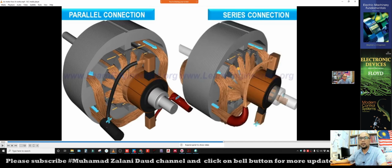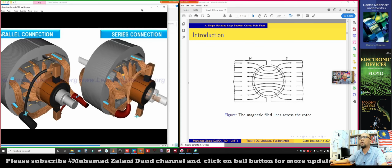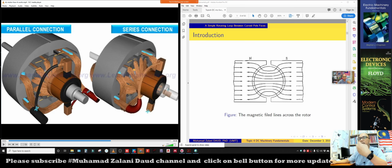Okay, so as you can see in that video, whether it is a motor or a generator, it works the same way, where the commutator is used to convert the AC behavior inside the machine into the DC output. That is the function of the commutator. It was also mentioned in the video about the armature. Armature means the windings of the rotor. We normally say armature windings, meaning that we are referring to the wire loop that we use for the rotor.